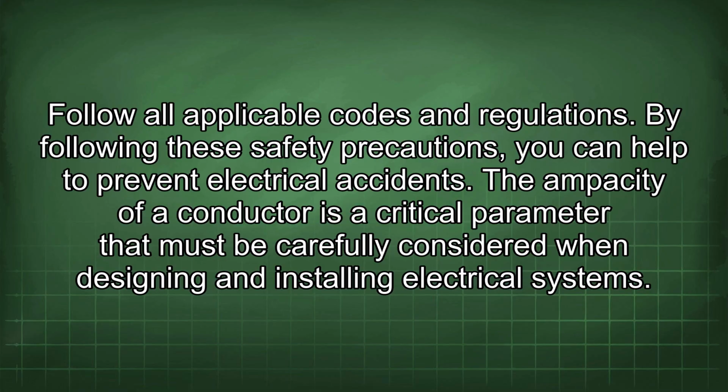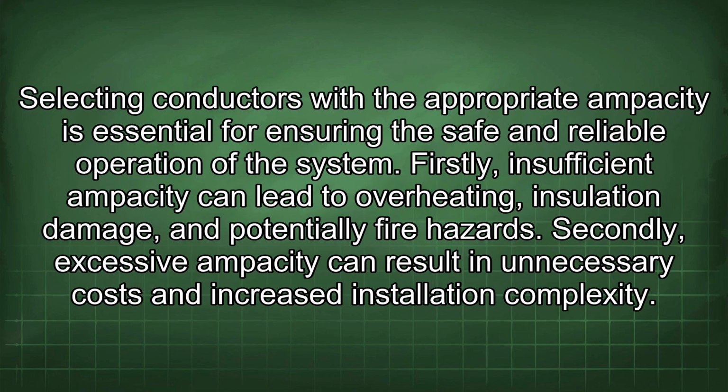The ampacity of a conductor is a critical parameter that must be carefully considered when designing and installing electrical systems. Selecting conductors with the appropriate ampacity is essential for ensuring the safe and reliable operation of the system. Firstly, insufficient ampacity can lead to overheating, insulation damage, and potentially fire hazards. Secondly, excessive ampacity can result in unnecessary costs and increased installation complexity.